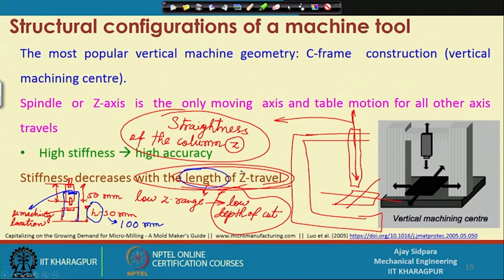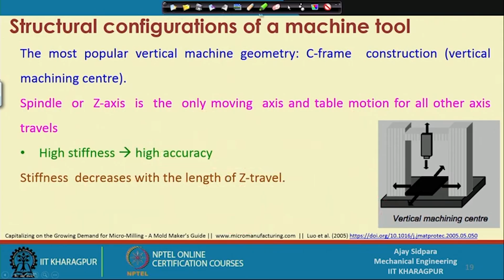That is the only reason, but our machining depth will obviously be low. But when you are putting a big workpiece or a long height workpiece, at that time it is an issue. That is not a problem every time, but sometimes you have to think about what components you are planning to machine with this particular machine, and depending on that you have to design the Z axis.